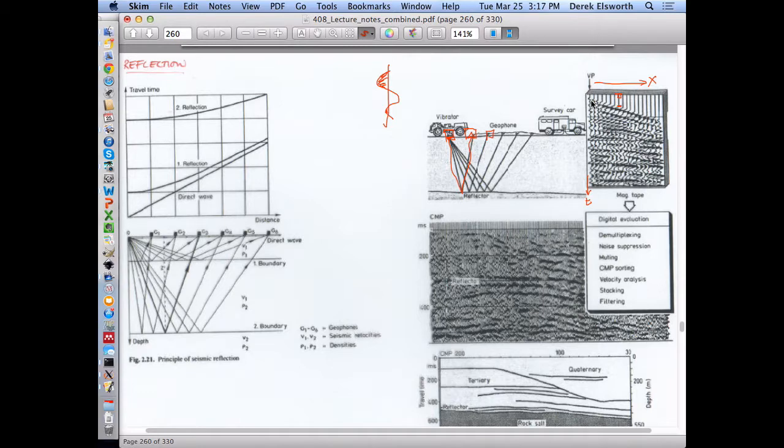And so what you can then use is this slope as basically an indicator of the first arrivals. And if you can correct that for the length along the traverse of what this individual distance is, you can make this now into a feature which accounts for basically the idea that these would represent stratigraphic boundaries. And so I suppose what you need to do, this first arrival represents when the reflection comes back to here.